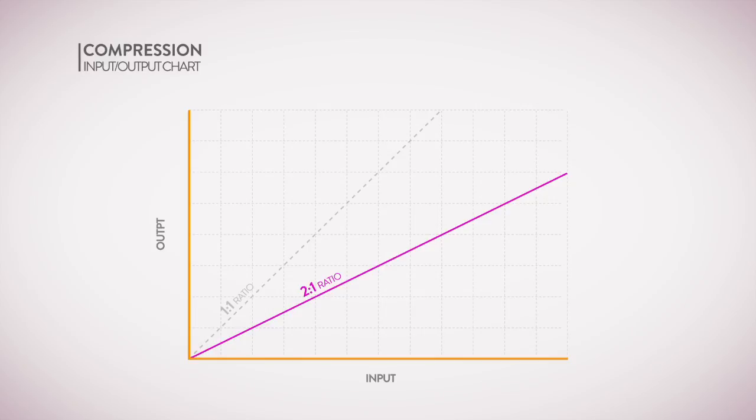A compressor splits the world of input effectively into two halves. There will be one half below the threshold. This is the second most important knob on a compressor. We set a regime change. Below the threshold, we do no compression. We allow the world of 1 to 1 to be maintained all the way up to the threshold. If you make 1 dB more effort, there will be 1 dB more output, 1 dB for 1 dB. Below the threshold, therefore, we are working with linear acoustics.